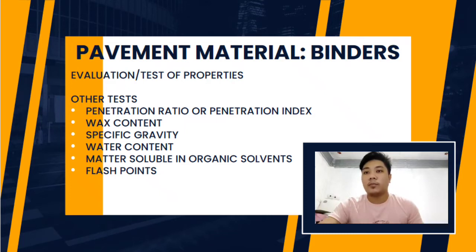Next, wax content. It may give negative effects in bitumen like increased sensitivity to cracking or plastic deformation in asphalt concrete pavements, but in other cases, wax may even show positive effects on bitumen, such as increased stiffness at higher temperatures, leading to improved resistance to rutting.